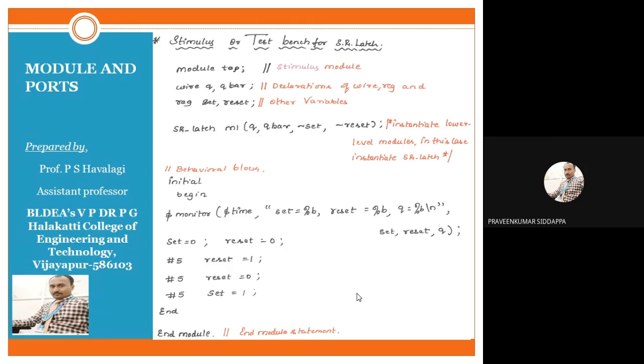So first we should write the behavioral block. How do we identify a behavioral block? By seeing initial and always. In your code, these two syntaxes should be present. Then that code we call behavioral code. Remember it, those are behavioral description code. First we have written an initial. Why? Because initially we are providing the inputs, so we have used initial.